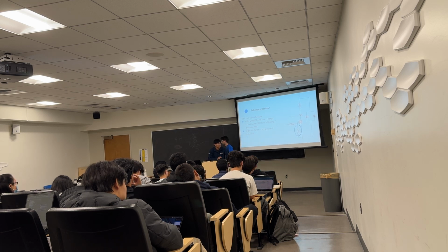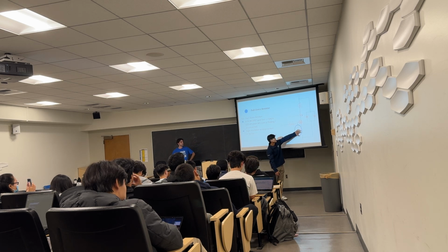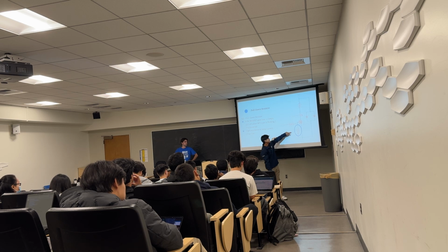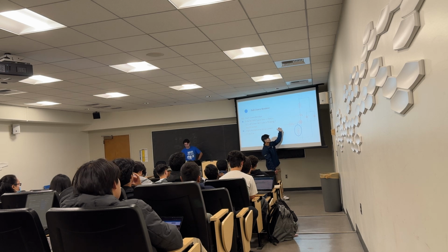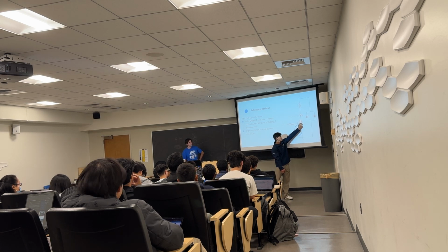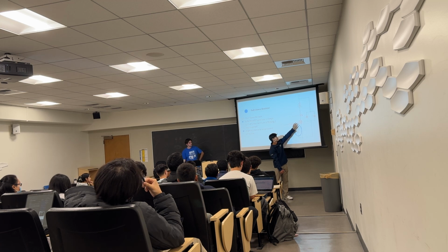Just to restate what Michael said, we're explaining why we need this path at all. Would it still function even if we didn't have this path? Right when you turn off the MCU, current's still going here, and there's current here that has a path towards ground, but what about excess voltage here? Where's it gonna go?